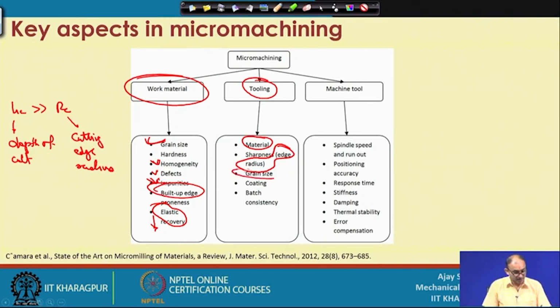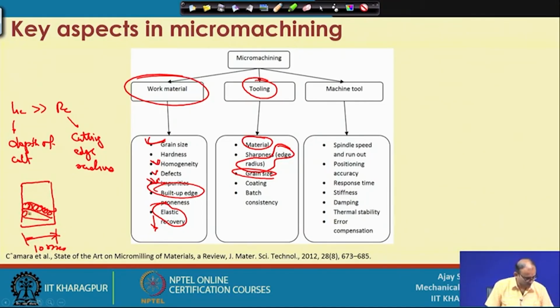Correct. Grain size of the tool is important, because we are using a very small tool. This is considered a very big tool in micro machining. So, it is considered as 10 mm, right. So, we are using a very coarse grain cutting tool, tungsten carbide, let us consider. Now if you go from here to 100 micron, then only 2 or 3 grains will come into this particular part. That means its strength is also very less. So, you have to use very fine grain tungsten carbide particles, so that you get enough particles to maintain that stiffness for a longer time.